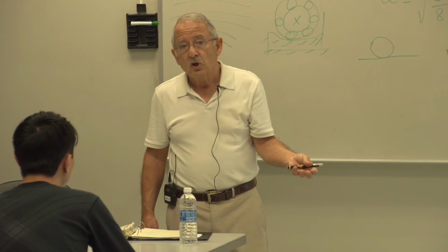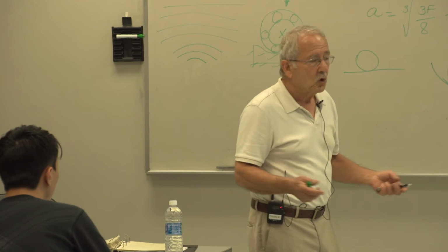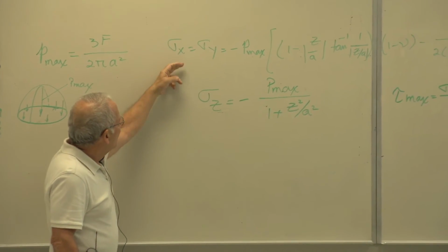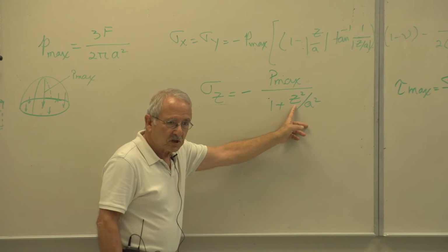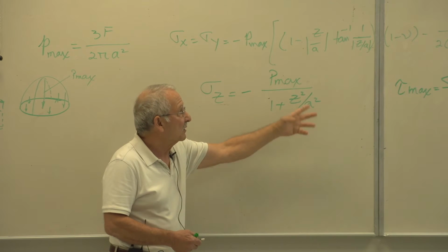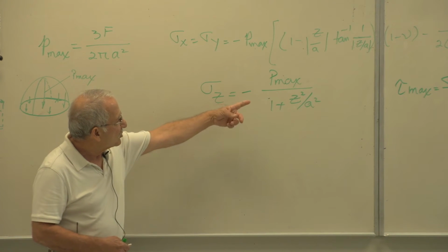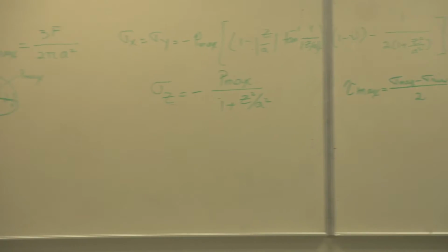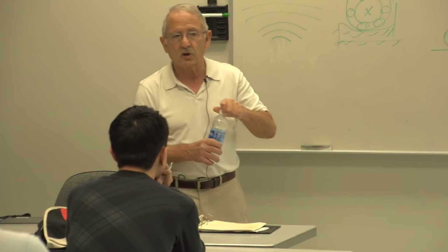If, however, the value of nu is not 0.3, it is some other value, then you essentially need to draw a graph such as this for that value and do the same thing. Or do it analytically. Find the 3 shear, in this case you only have 2 because those 2 are equal. Find the shear stress by saying sigma z minus one of these divided by 2. Take the derivative of it with respect to z, set it equal to 0, find the value of z, and if you do that for this, you'll get 0.5a. But for any other nu, find the value of z and then put it back into the equation of tau max equals sigma max minus sigma min over 2 to find the maximum shear stress in that case. That's how these are found. But a graph is actually much more telling than just plugging numbers into equations.